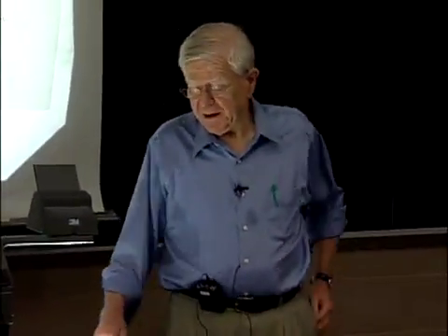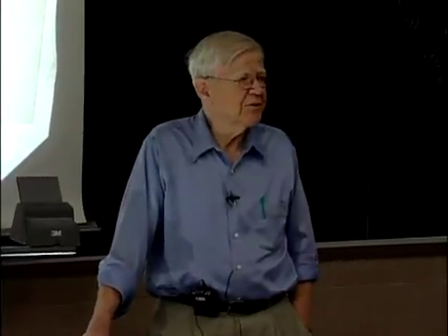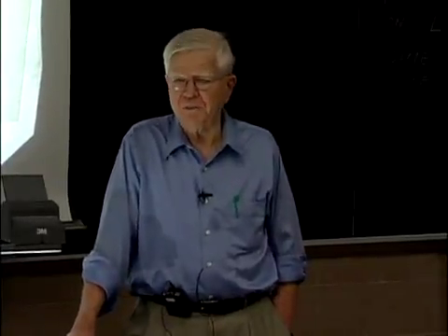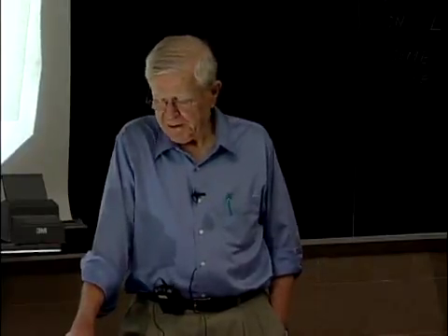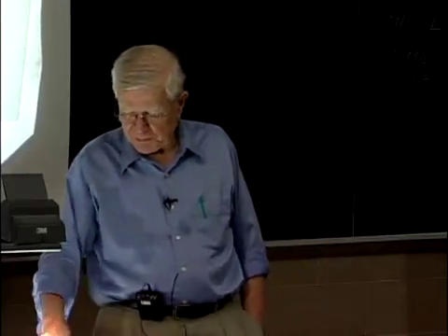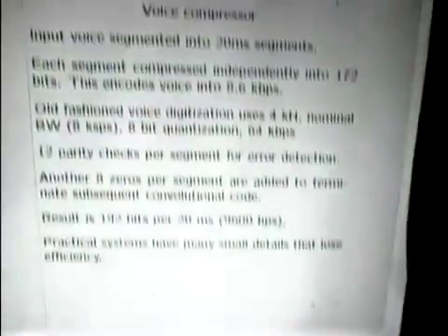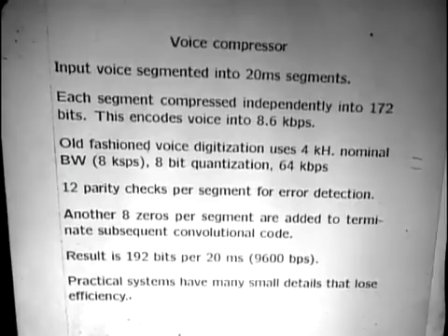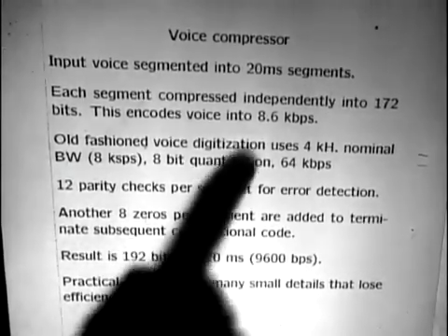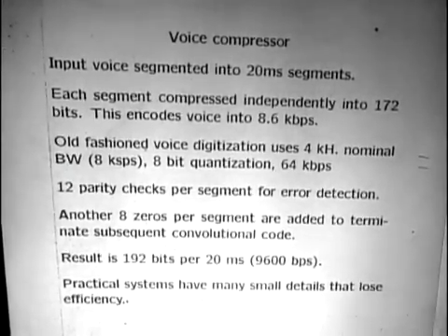Well, anyway, what this does is it takes each 20 millisecond segment of voice and it maps it into 172 bits. And what that means is if you multiply the 172 by the 50 segments that you have per second, it comes out to be 8.6 kilobits per second.